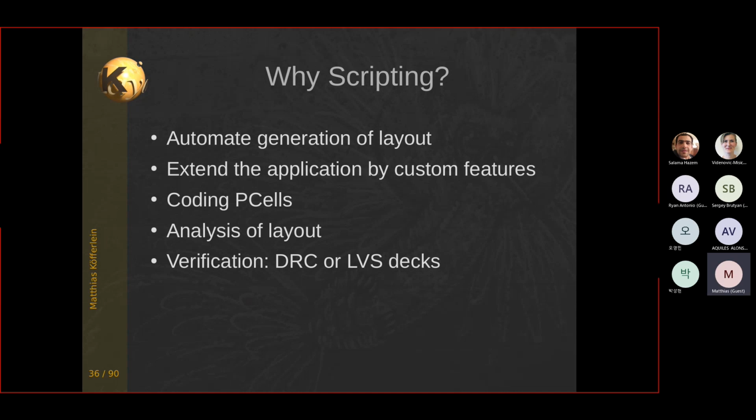There are some more applications for KLayout and scripting. Some people use it to extend the application. So instead of just generating layout, you can also create new menu features, like functions which manipulate layout in certain ways, or do other things like asking databases. People have done a lot in that respect. So it's not just confined to layout generation. If you know Cadence, you know Cadence also has a way to generate user interfaces. KLayout has the same features built in.